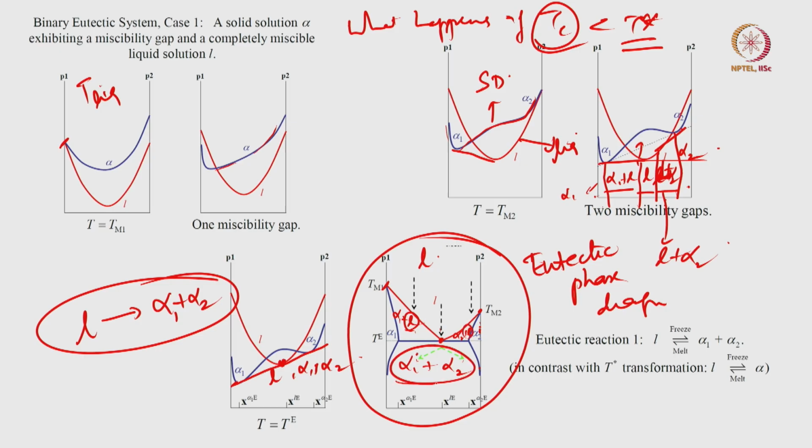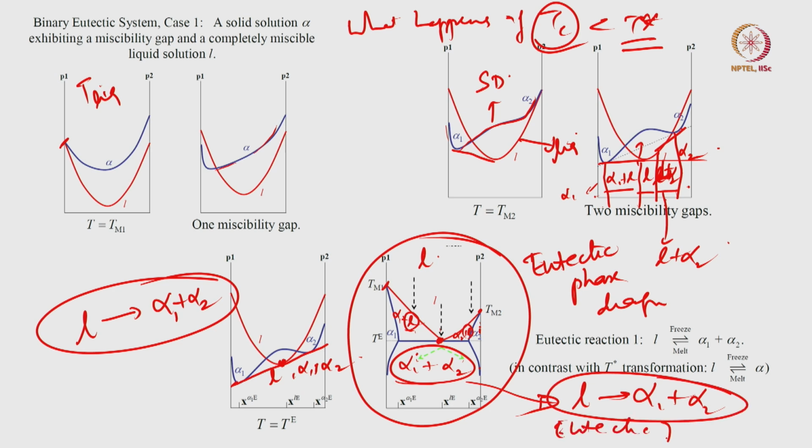So, what I have is a material which is inhomogeneously split up into alpha 1 and alpha 2 phases. This point where three phases coexist, and liquid gives rise to alpha 1 plus alpha 2, is called the eutectic point. But now you can understand the eutectic again by thinking of a regular solution.